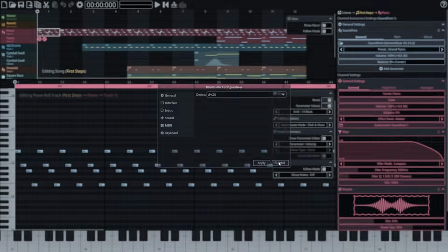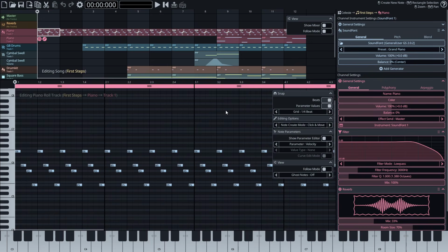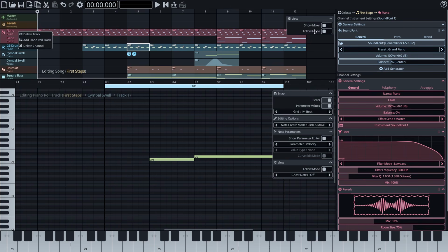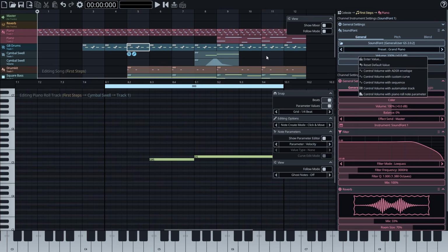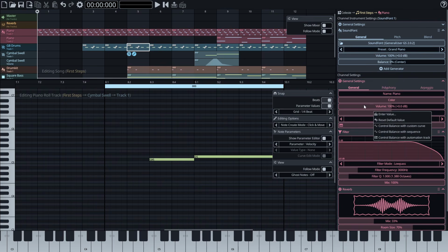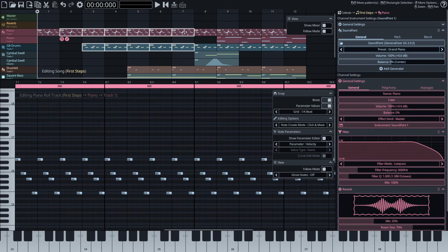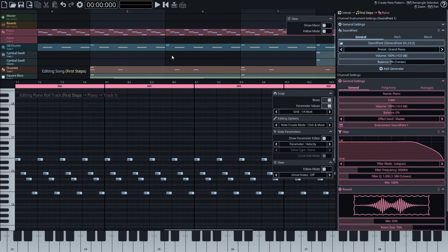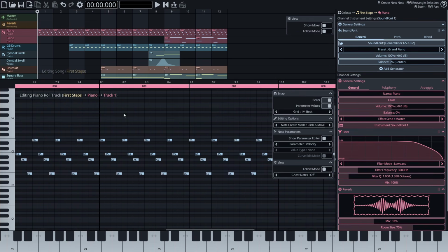Now for the basic mouse control, for now all you need to know is the left mouse button usually creates stuff when you click, and a double click will often delete those things. The right button is used to open context menus when clicking. Please right-click on everything you see. A lot of features are only accessible through these context menus. The right button is also used to make selections. Simply right-click, hold, and draw a rectangle. Finally, the middle mouse button, the mouse wheel, is used for navigation. Scrolling the wheel zooms in and out, and pressing the wheel pans around the various views.